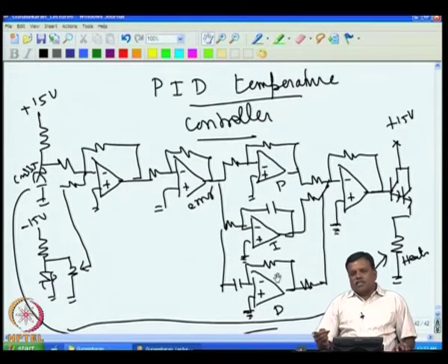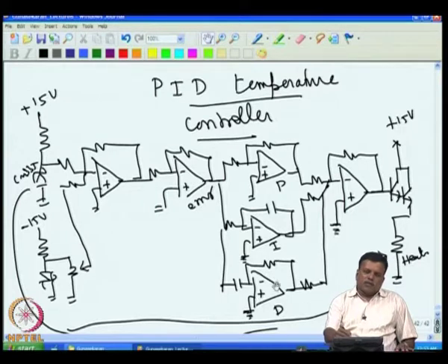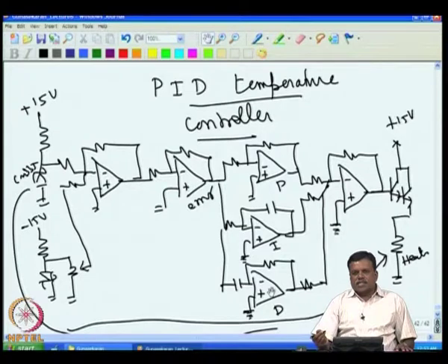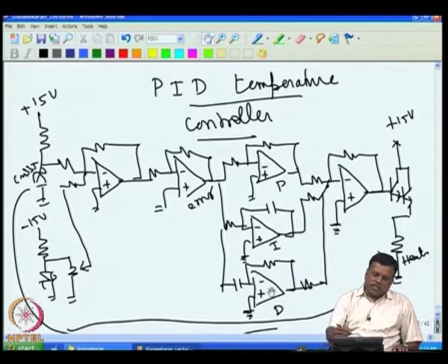So it is always advantageous to add a differentiator, and if I match the differentiator to one of the time constants, one pole also gets cancelled, and oscillation of the system can be avoided. So the differentiator gives us two advantages: one is that it makes the system fast, and the other is that if I match it to one pole, the system oscillation can also go away. So what we do is we match this to one of the time constants.